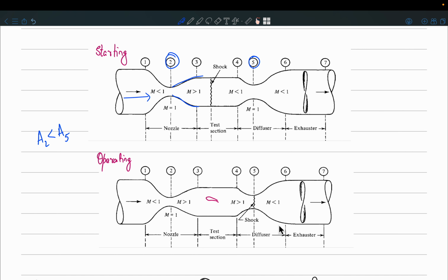Yeah, so the first thing that I said was no, it is difficult to operate at such high speeds. Another thing is, if you move the shock anywhere beyond this, again the area is going to increase, isn't it? And again the shock strength will increase. Then again more and more losses. After the throat of the diffuser, yeah.